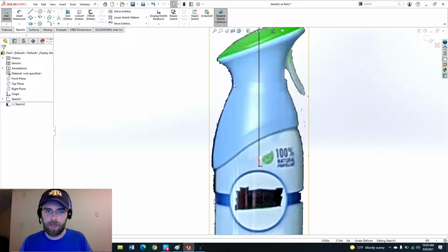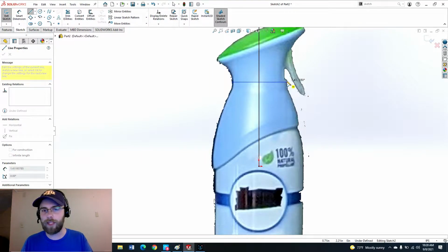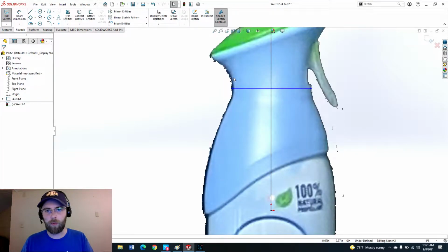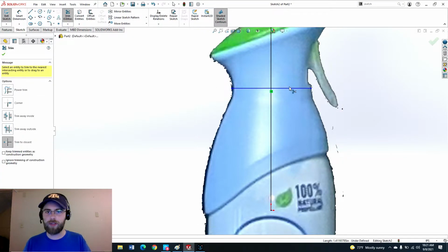And I think the best way to do this would just be a spline. But there is one thing we need to keep in mind. We've got this parting line here where we're going to go from a revolve to a loft. And we want to make sure that the curvature is continuous. So what I'm going to do is make sure that the spline starts on a vertical. So it's pointing straight down from this line. And that way it'll be easy to bring up the curve with the loft so that it's just coming straight up from that point. So this is the top of our revolve feature, this line here. So we'll just cut this off right here using the trim tool.